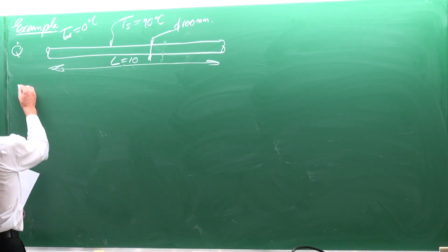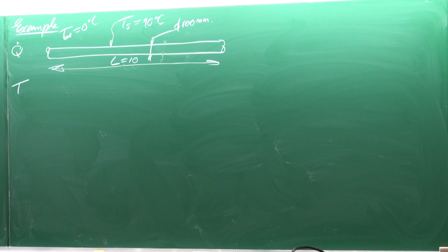If we just think of Grashof numbers, we can immediately see there's a viscosity value that we need, there's a beta value that we need, so we know the properties are always an issue with these things. It's one of the first things that we need to get, because as soon as you get them, you can start doing calculations. So, we choose the film temperature as the point where we're going to calculate the properties.